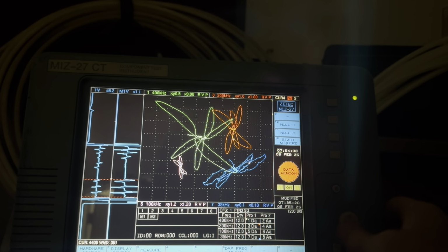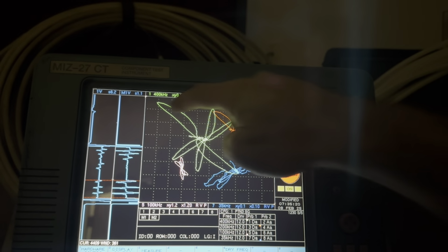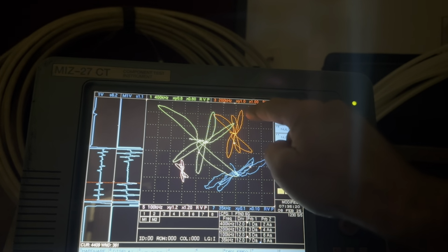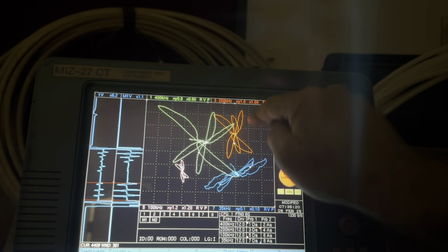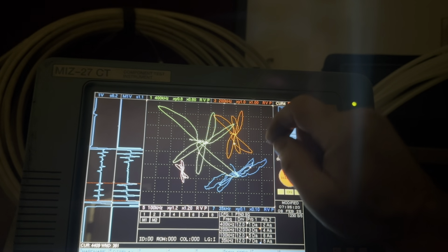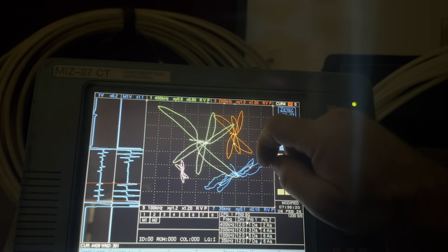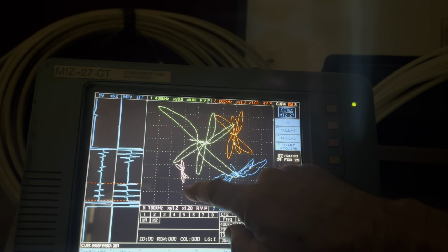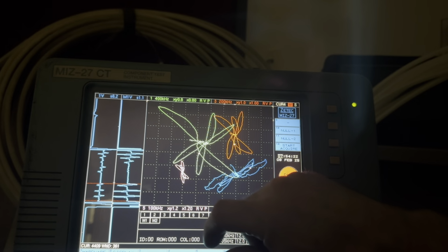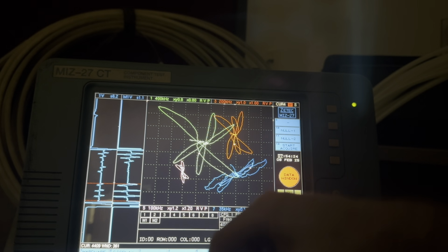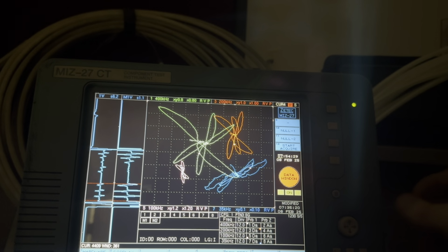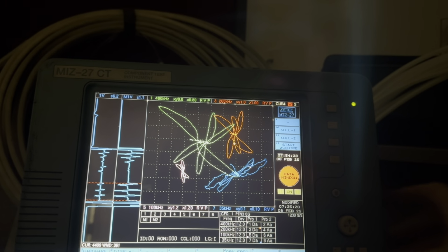on the various frequencies. So a lot of phase spread on channel 1, 400 kilohertz. Less phase spread on channel 3, 200 kilohertz. That's the F90 frequency, best used for detection. The green here, that's the high frequency, best used for sizing. The purple data here is 100 kilohertz. That's used for creating mixes, confirmation channel. And then channel 7, that's usually used for a locating channel to help you figure out where you're at along the length of the tube.